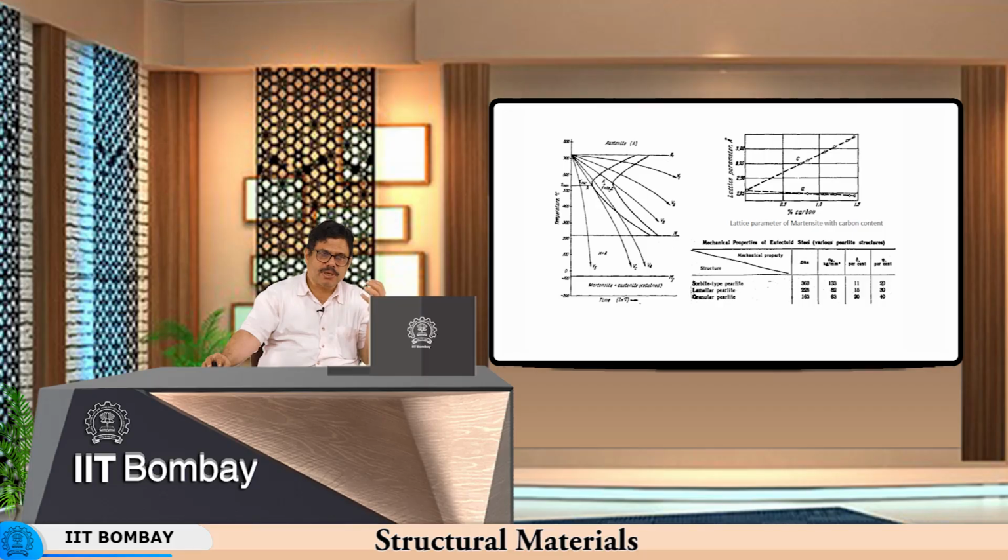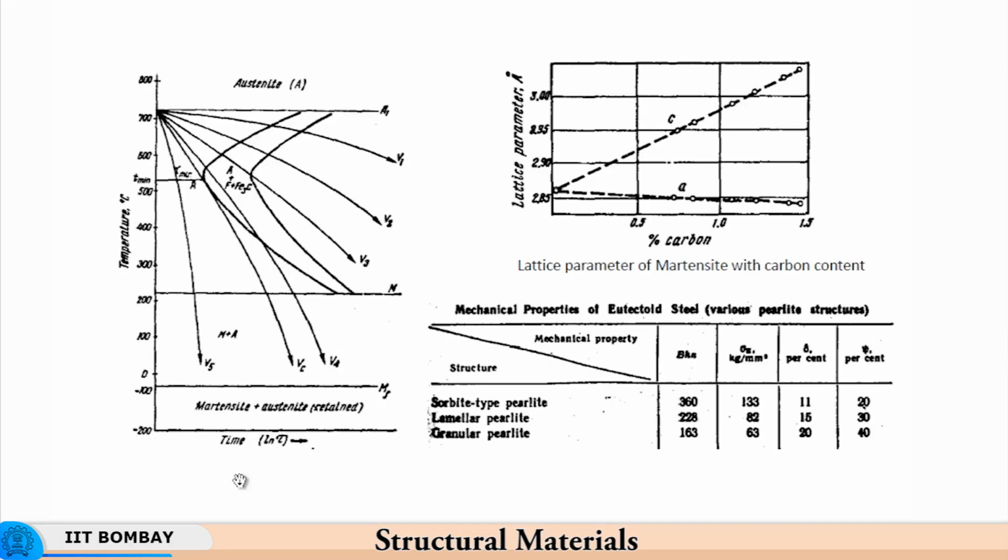This is what happens when you use the same kind of material for crushers and things like that, where wear resistance progressively grows with additional use. Initially the wear resistance is relatively small because the material is relatively soft, but as the working takes place, as the strain energy is supplied to the material, strain-induced martensite gets formed. And this happens with many kinds of materials, where you do not want failure of the material; you want the material to withstand a very high amount of strain.